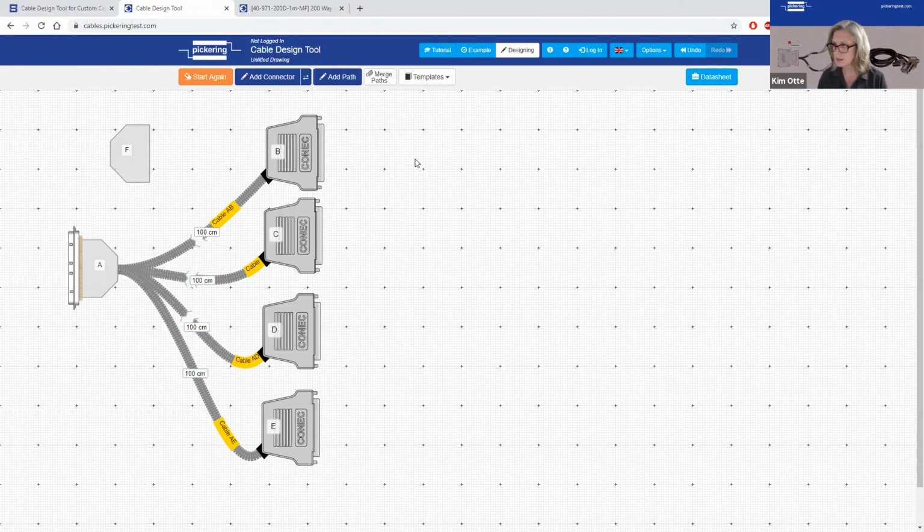When producing a long cable, say 3 meters long with many twisted pair and single wires in the cable, you need to twist the cable for flexibility. Where is this specified? That would depend on the bend radius of the internal cores in that cable, and I guess on the external screening as well. So that information would be in the documentation on the wire type.